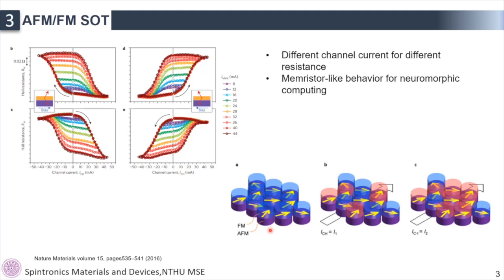The bias directions of individual grains are random, and the aggregation of the grains exerts a unidirectional anisotropy in a collective manner. When a channel current is applied, we expect that all the grains lead to the SOT switching. However, the grain boundaries with different bias directions interrupt the domain wall propagation across the crystalline grains. Thus, the reversal is confined in a unit of crystalline grain as the channel current increases, and eventually the intermediate resistance states may be stable.